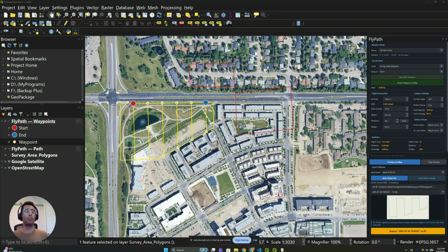The only important thing that I need you guys to keep in mind is to turn on the interval photo shooting before starting from the first waypoint and make sure that it's actually activated and running. This is actually what takes your photos during the flight, and no photos means no map. So don't forget to do it.